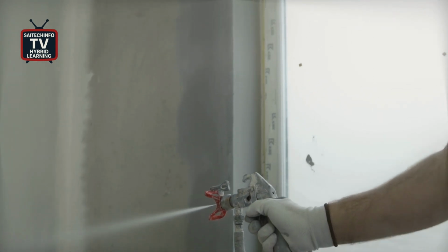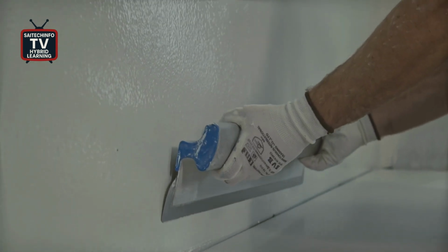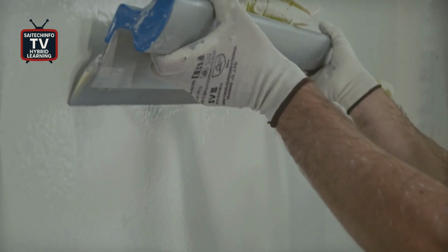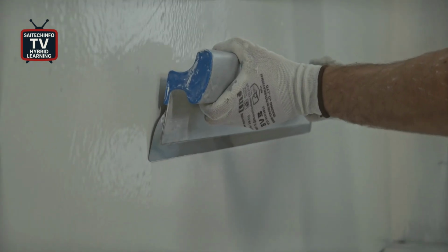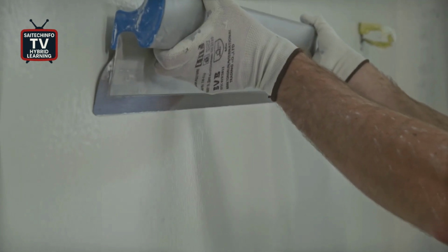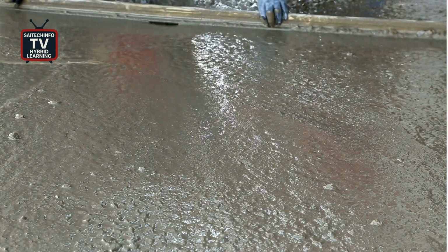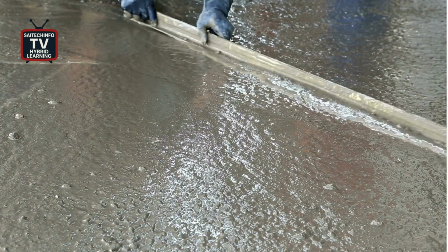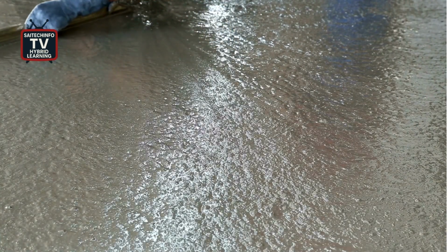densifier in coatings. Then some of the precipitated silica are applied as matting agent and anti-settling agent, so that it has got some thixotropic control in the paints and coatings. So it's a very good rheological modifier, and this will be useful for arresting the sagging in paints or coatings, that is anti-sag agent.